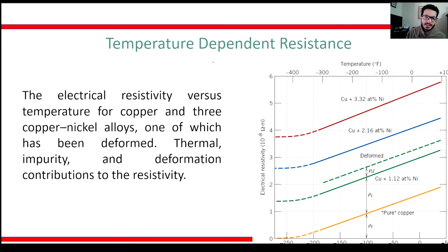And we were saying that temperature is a key aspect of resistance and conductivity in most physical quantities. So we talked about positive coefficients and negative coefficients. A positive coefficient means that when you have a temperature increase, your property increases, and a negative coefficient means that when you have a temperature increase, your variable decreases. So for instance, this is a positive coefficient because we increase temperature and our electrical resistivity increases.